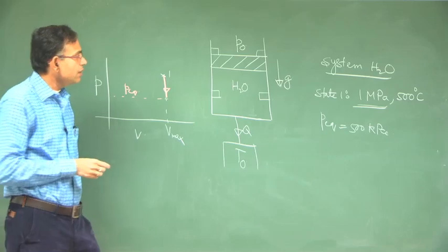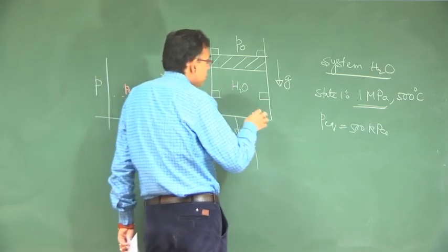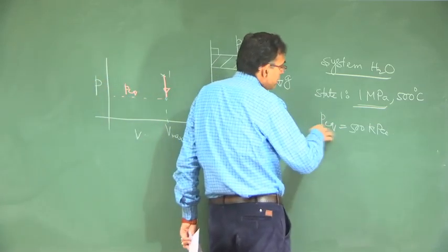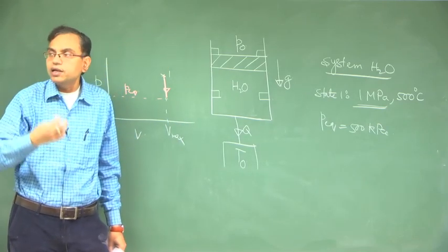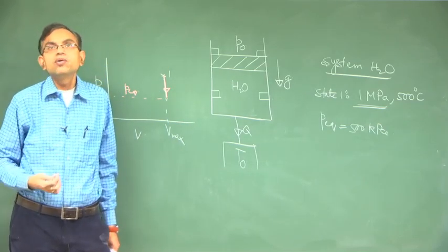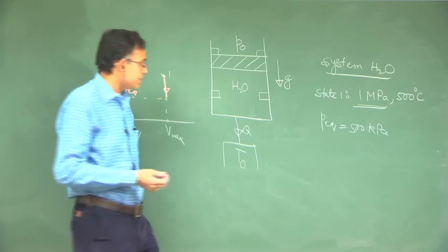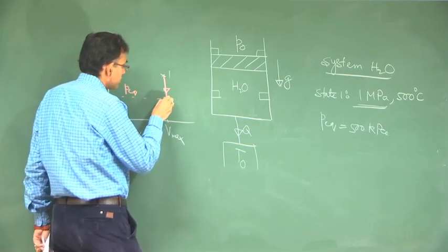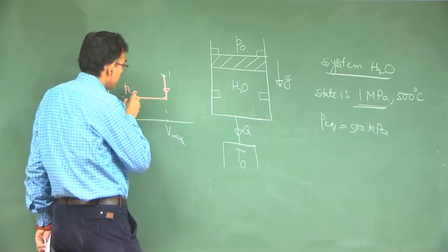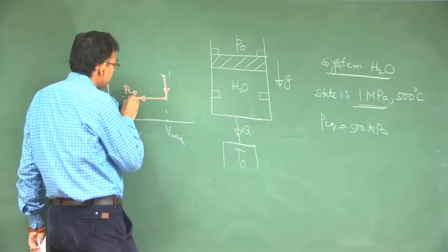When it starts moving, it will move with this equilibrium pressure, because the resistance pressure does not change, the internal pressure also will not change during the quasi equilibrium process. Question is, does it hit the stop?